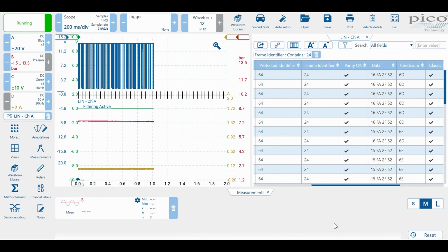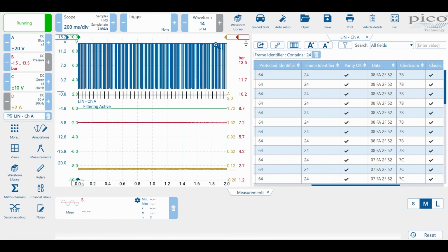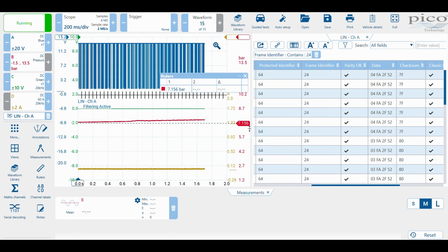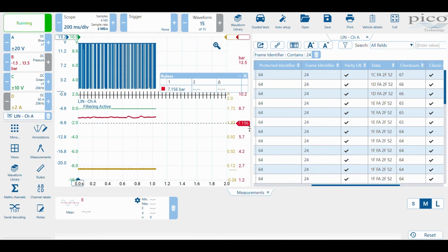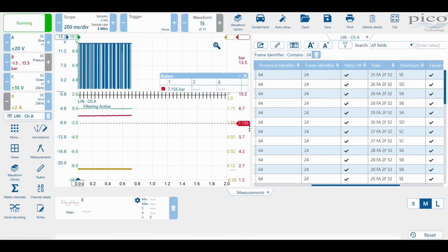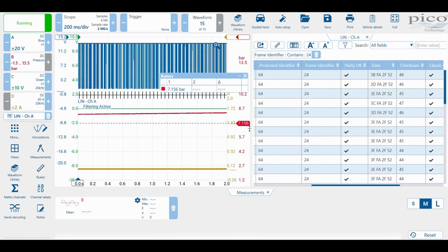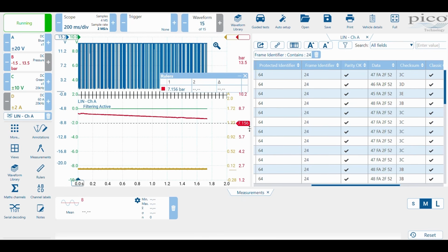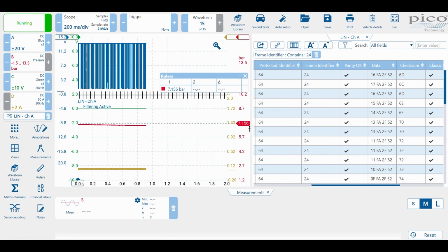We know we are only interested in our protected identifier, frame ID. And if I pull a ruler in here as well, we should be able to see transitions in pressure. Yeah, and the only byte that's changing is that first byte. Oh no, actually the second byte has now moved. So now that's gone to FA. Nevertheless, it would appear that our pressure is directly proportional to that first byte.